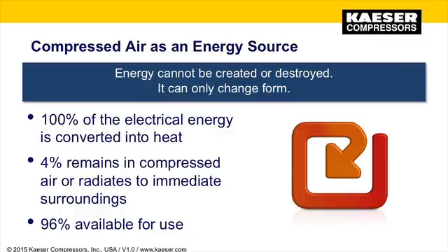The first law of thermodynamics and the law of the conservation of energy state that energy cannot be created or destroyed. It can only change form. So for compressed air applications, the air that enters a compressor at atmospheric pressure has a base level of energy content. After the compression process increases the air pressure and raises its temperature, the energy becomes available for transfer. The heat must be removed to maintain proper compressor operating temperatures and to cool the compressed air to make it suitable for planned use.